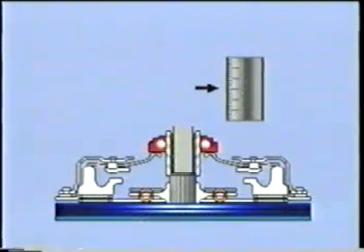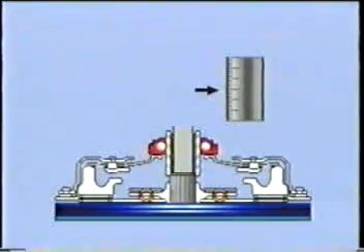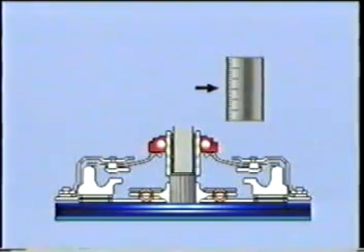If the hydraulic clutch system can't develop adequate pressure, bearing travel will be less than the specified amount and the clutch will not fully disengage. This can cause gear clash or a hard shift problem.